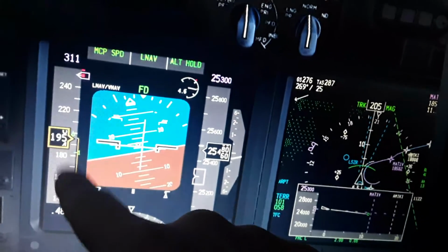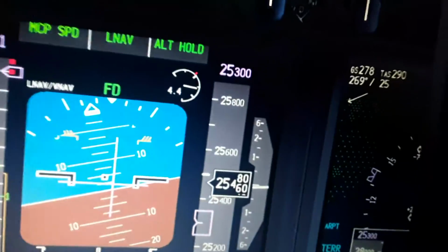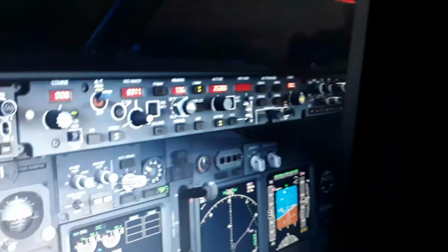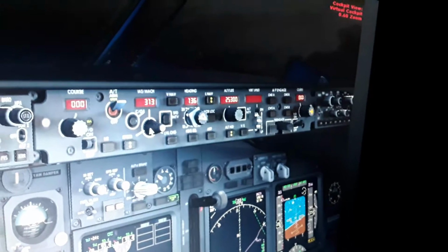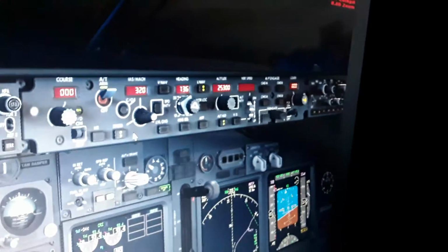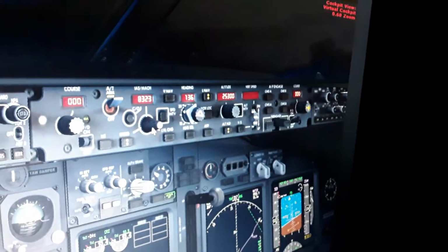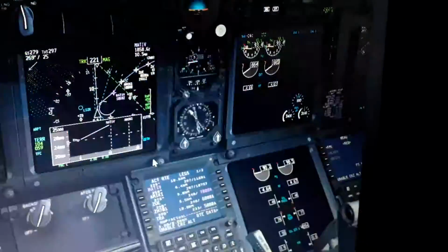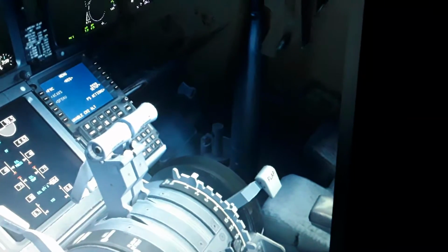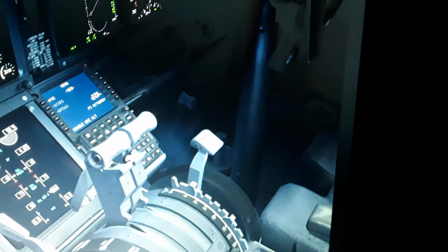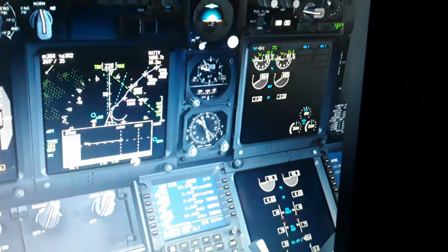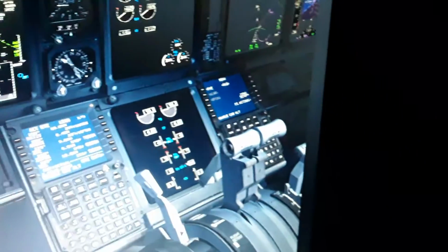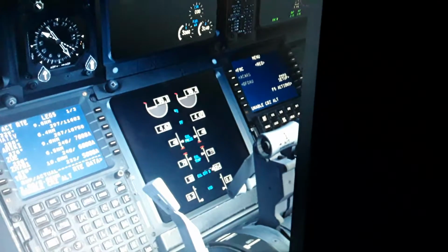This is how we avoid the stall speed, by increasing the thrust and leveling the aircraft from climbing. So I'm gonna use more airspeed right now, more thrust. Hopefully, and retract the flaps we don't need right now. Turn back to the airport. This may be a direct route into the airport.